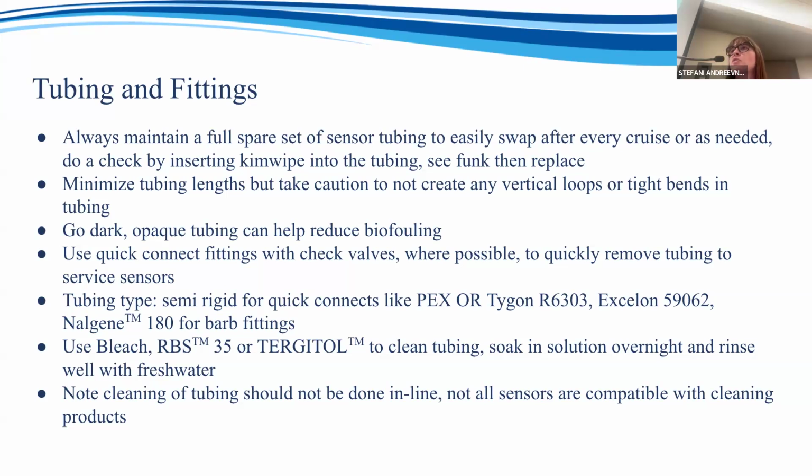I see a lot of clear tubing on systems, and it's good because you can see when biofouling happens, but it's bad because it helps promote biofouling. So do the pinky test instead. Use quick connect fittings. Oh my God, I love quick connect fittings, unions, whatever, that make it easy for you to take that off, check it out and put it back on.